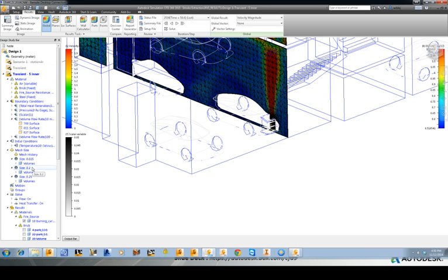A lot of times manual meshes for these kind of analyses are handy because you don't necessarily know where the flow is going to be going. As many have probably seen when you use the automatic mesher, the core or the middle of these large rooms end up being extremely coarse, and that can sometimes be the instability points in your models. There's just too much mesh, you have all these different flow profiles going through. So sometimes sticking with a manual mesh, adding in some refinement regions near the hot fires for these kind of models, ends up being a great place to start.